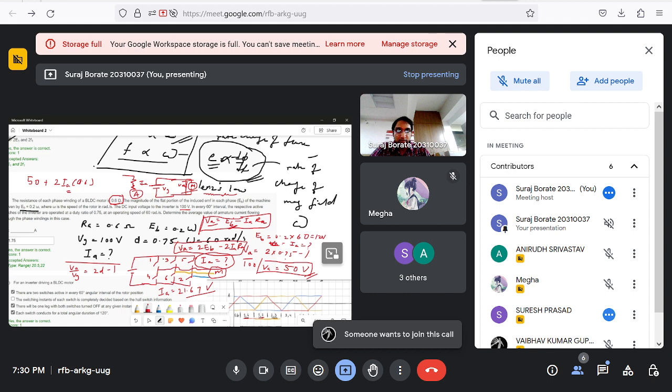So you cannot have just plus or minus and connect to the motor. Actually, there are three wires that come out of the motor. There is no two-wire. In a DC motor you had only two wires, plus and minus, you give and you get it. Now you cannot give plus and minus here either. Why? Because then it is required that this becomes minus sometimes and this becomes plus sometimes. So it is alternating. The polarity is alternating. You cannot have plus always over here and minus always over here.